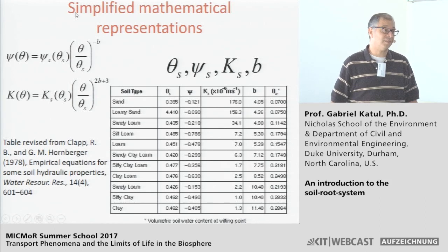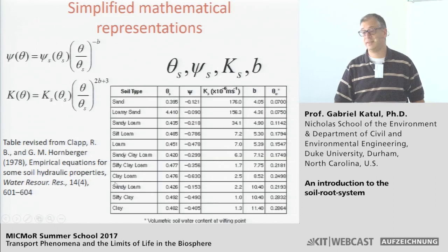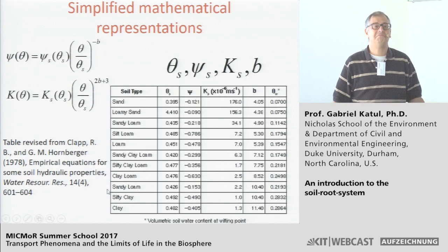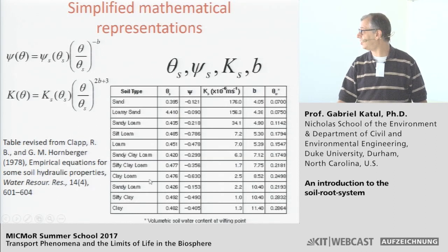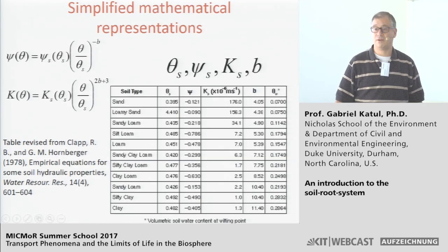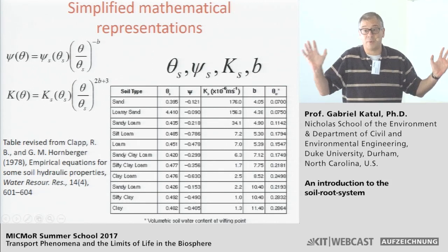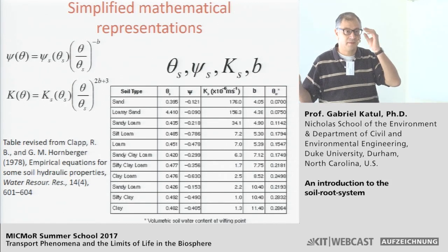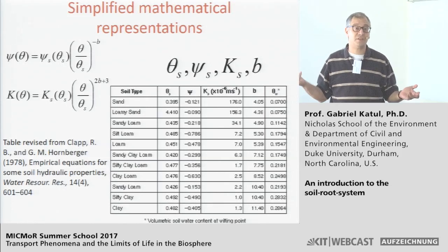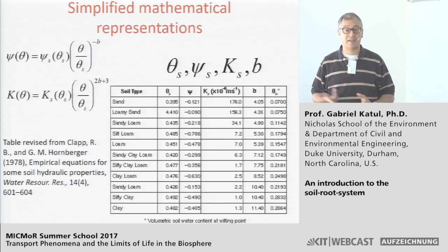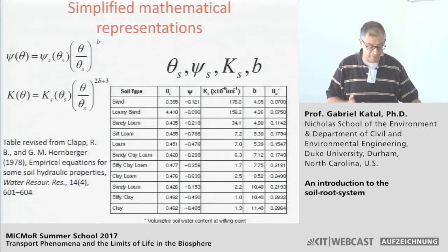So you could see the challenges that are confronting the soil physics community. So even though you may be putting one number here, in fact, the spatial variability of those quantities is huge. No surprise if there are roots, if there's a little bit more soil compaction. How accurate are really your soil maps? These are disturbed samples, they're not intact. You disturb the soil samples, you are disturbing the pore structure, period, yeah? You are not taking an intact pore structure, which is so crucial to definitions of retention curves and hydraulic conductivity. So this is the problem in soils, in a nutshell.